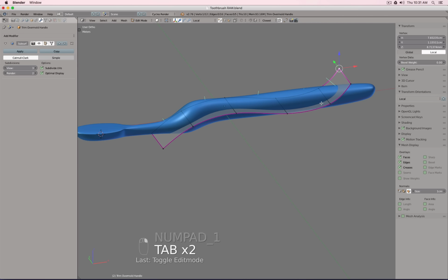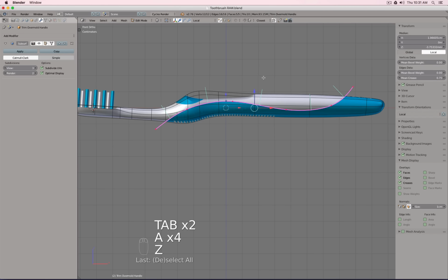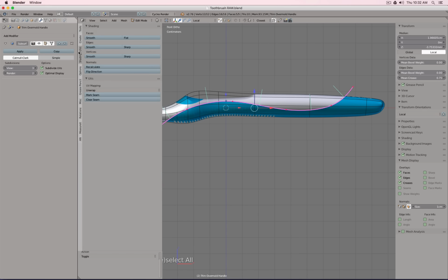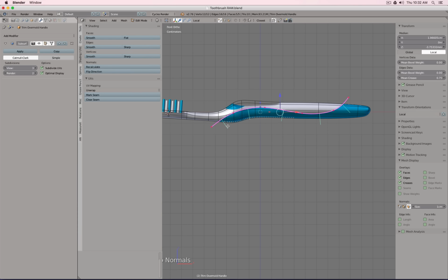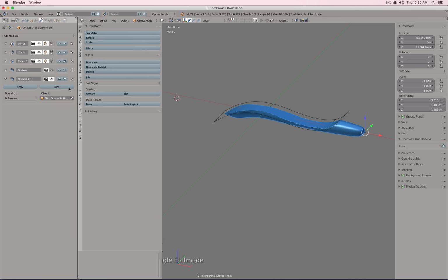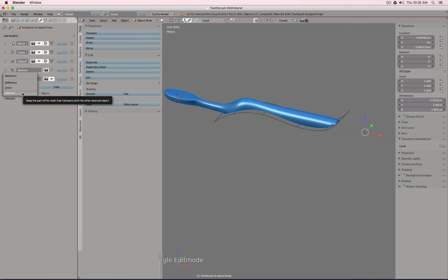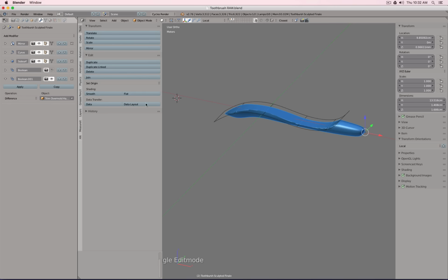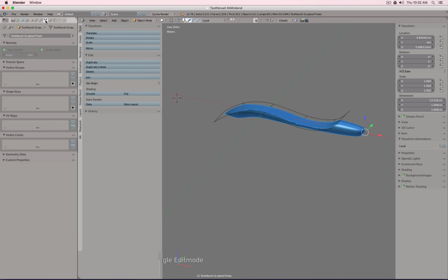Okay, but the normals face up, and actually I would like to maintain the other area. So there are two ways. I could simply make use of my normals to see how they look, and then say flip direction. Now you see they face this way, which means they will keep this part of the geometry. I could also simply have said flip the intersect and difference. That's the second way how we could do it.